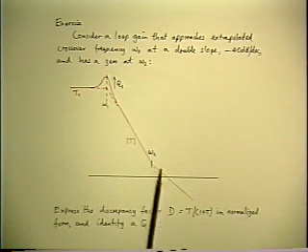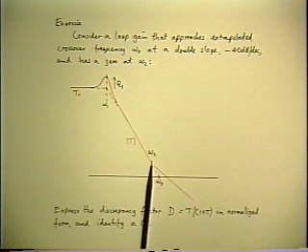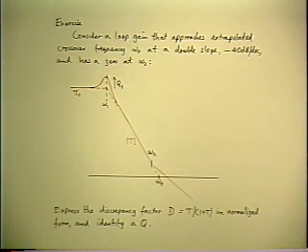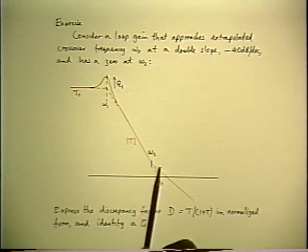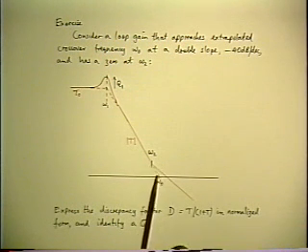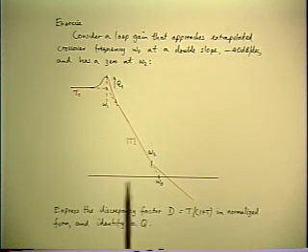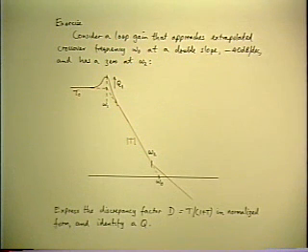Because small or even large changes of the ESR make correspondingly large changes in the stability margin, so that's violating the second answer to that question: how much margin do you need? It's directly sensitive to an uncontrolled second order parameter. So that's a horror story, because it's a combination of all of the worst things that you can do. And it's especially ironic, isn't it, because the second vendor was giving them a better capacitor.